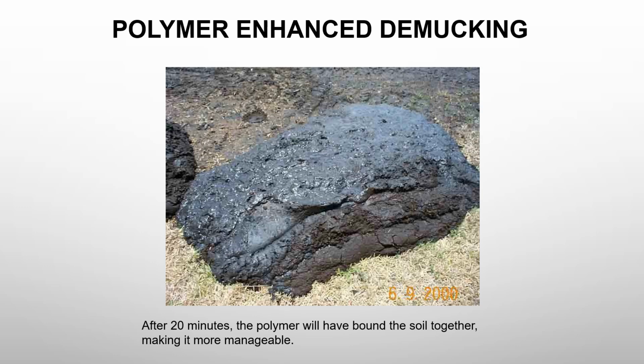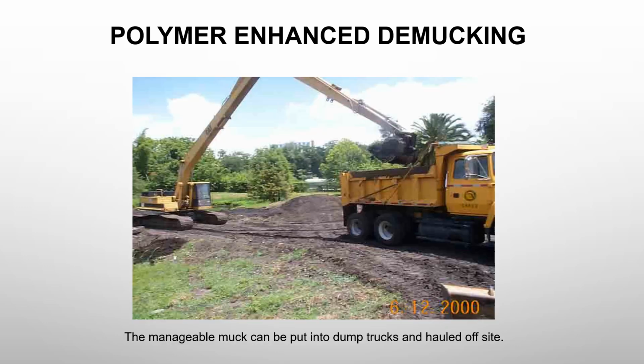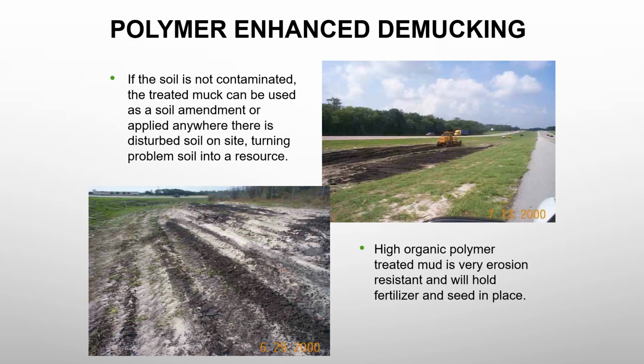And then what happens is it will solidify those into a very manageable material that can be easily picked up and hauled away. So you can put it in and haul it off site, as long as the sediments themselves aren't contaminated. There's no special disposal considerations with the polymer. It's non-hazardous, so this can be a really cool application to help save time and money when dewatering basins and removing and cleaning out basins and things like that.